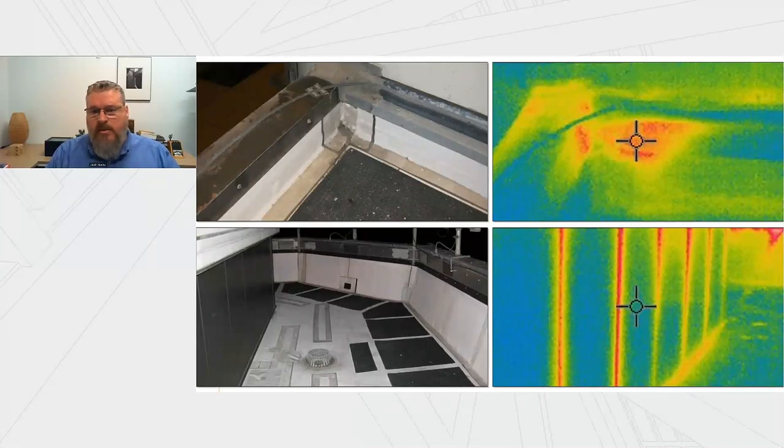So what you do is you test in one direction, take your images, then you turn off the air pressure and let it sit for 15, 20 minutes. That's usually enough. It depends on whether or not you've got a thermally massive enclosure. Metal panels change temperature back to ambient conditions pretty quickly. Then you run it in the other direction.